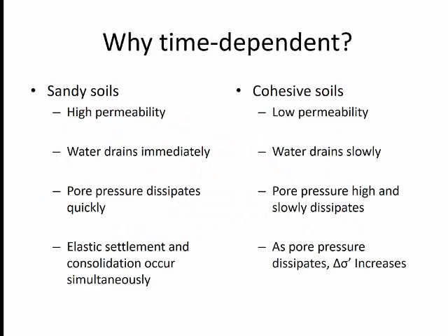Why is it time dependent? Well, sandy soils often allow permeability to occur very quickly. Water drains immediately, which means we do not have a change in pore water pressure that exists between the pore space or the void space that exists between particles as load is applied.